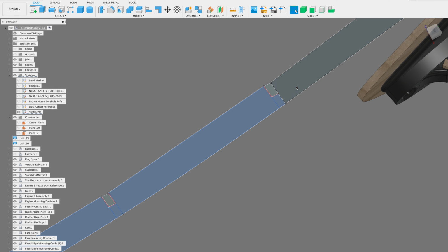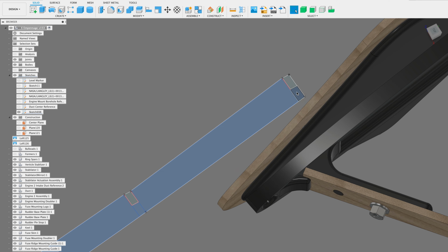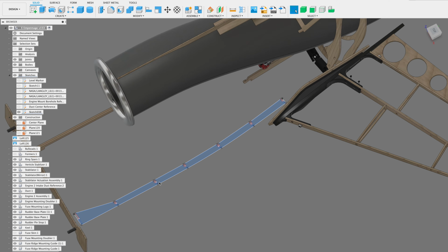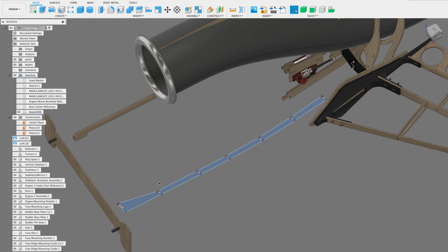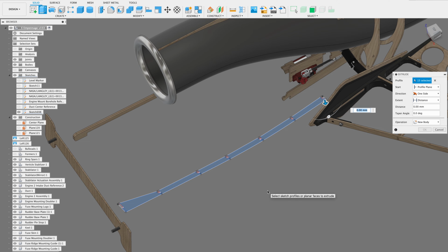And at the line, we want that, and there we go. So now you can see we've got our selections. Now using the E key for extrude, we're going to extrude this. Now, because we're working on an angle, we don't want to extrude just in one direction because we will get a lot of overhang that is actually protruding outside of the former.